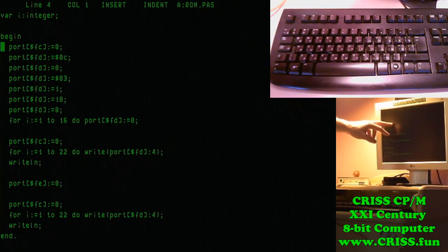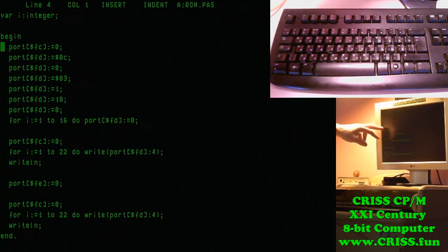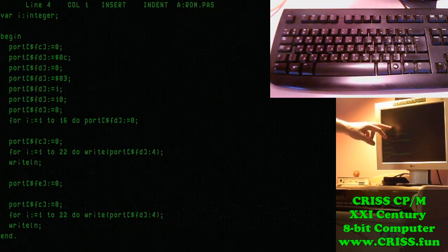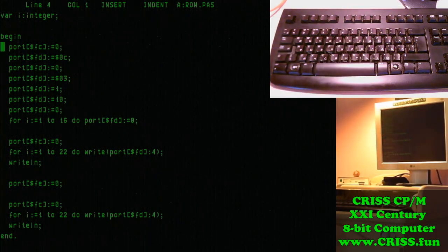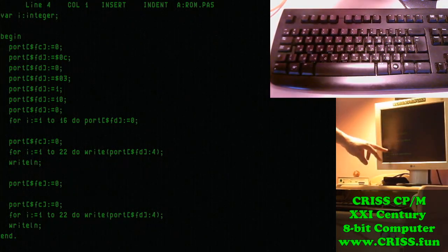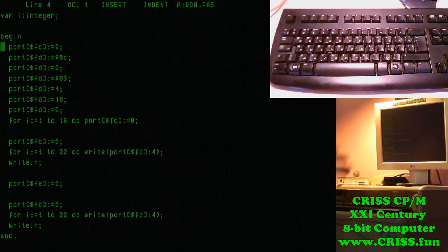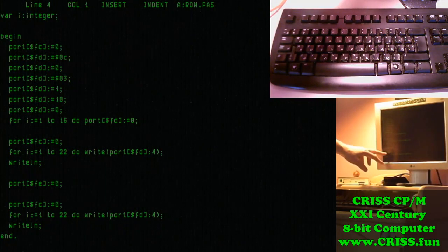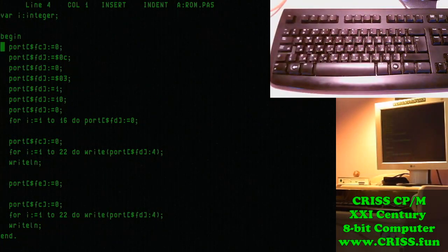Next we give a command to read, then we write down a certain address from which we will read. Accordingly, these are the most significant bits, then the middle and the least significant. By writing a 1 to the most significant byte, we will work with the upper half of the memory. After this we issue the command. FE equal to 0: this command executes a request to the SPI device and after that, just like we wrote, we read back the data that we received.